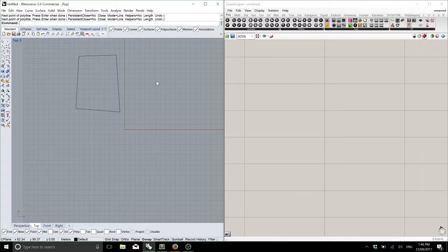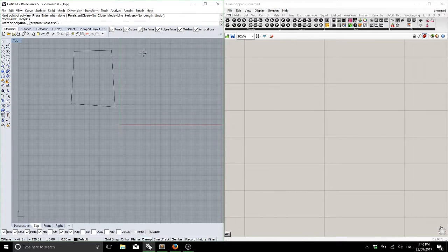The attitude that you have going into that is very much, oh, I'm only doing this once. And so you see there's a very different way of coding doing it once versus doing it lots of times. So when we draw these slab outlines or room outlines, we want to be working with at least 2, okay? You can work with 3 or 4 or 5, but we never want to work with just 1.